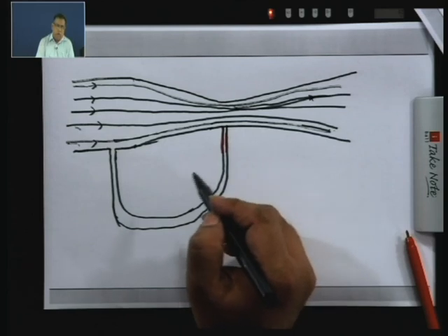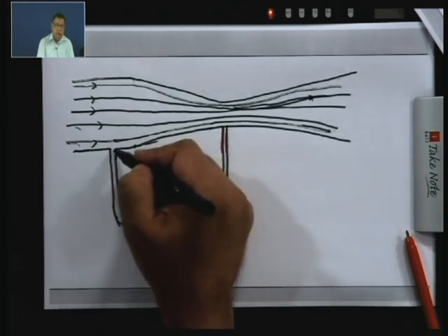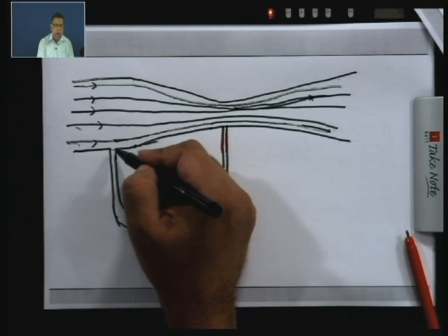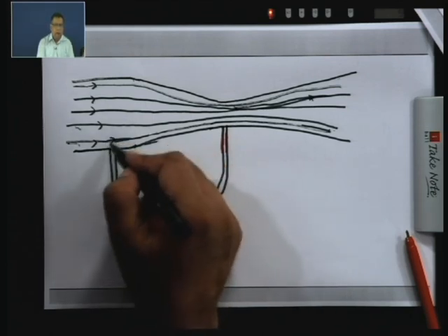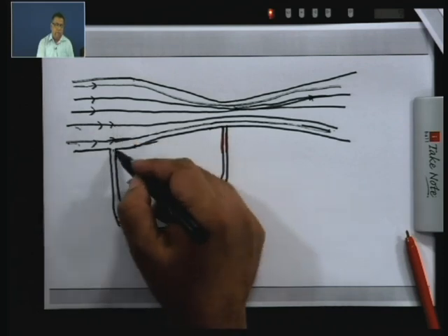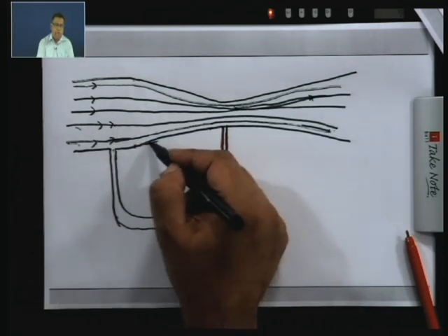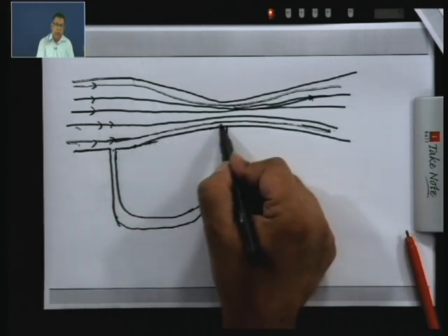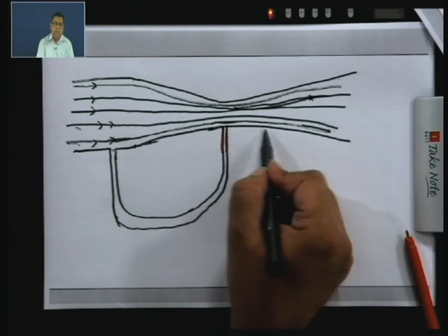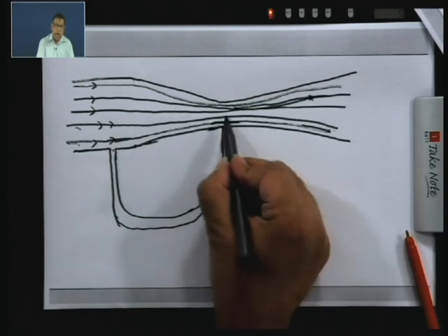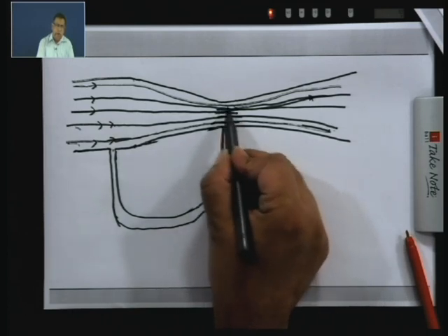Now, we will explain the reason for why we have placed the tap over here. This static pressure tap should be at a point where the streamlines are straight lines. We should not place the static pressure tap at a location over here, and here also the shape of the converging diverging section is such that the streamlines at the throat are almost straight lines.